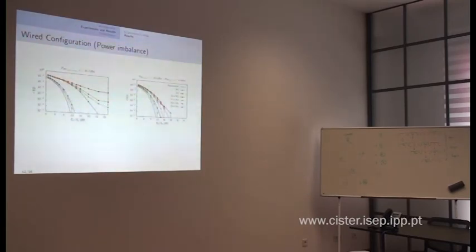And if now we do the experiments where we transmit these packets, like hundreds of thousands of them, and we do the statistics, we get these curves. You can see this is chip error rate versus signal to noise ratio. These are the errors that we will find in the original transmitted packet, and this is how much noise we are putting in.